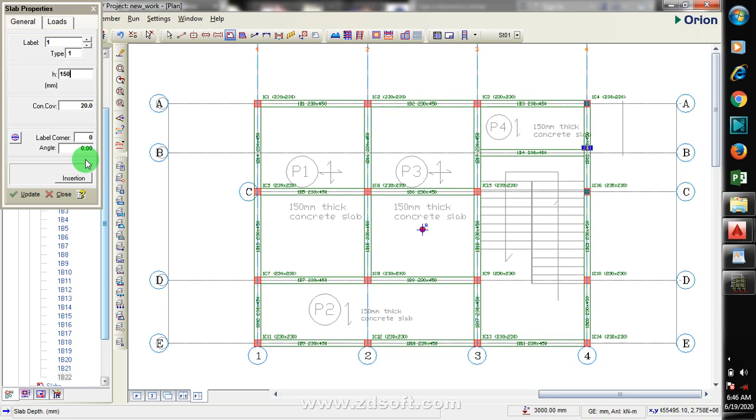I need you to know that for every structural member, the concrete cover you attach mostly varies. When you are dealing with a slab, the concrete cover varies from when you are dealing with your foundation base, for example, your beam, or your column. There is more to it. I would like you to lay your hands on the Reinforced Concrete Design book by Victor Oyenuga, or you can get Mosley and Bungey. They are good books that I know of. Or you can lay your hands on any Reinforced Concrete Design book that is recommended in your country.